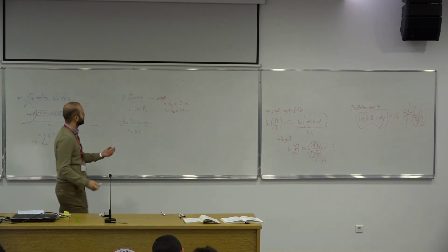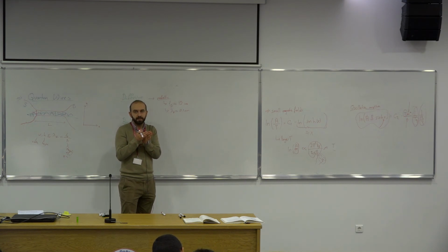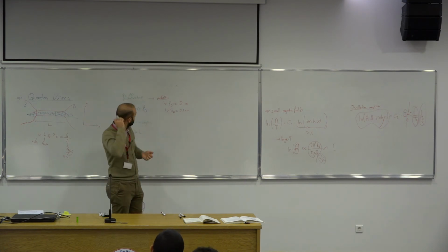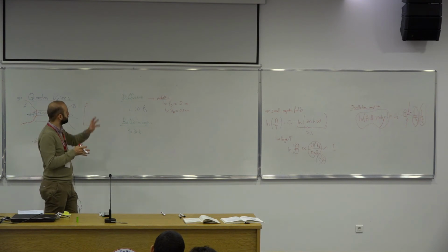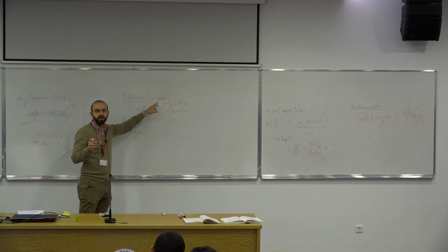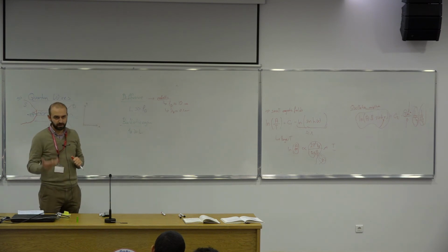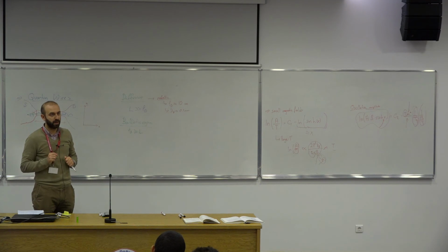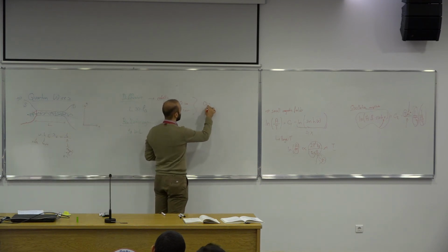So making such a short nanowire is practically impossible, because once you start confining your nanowire to such dimensions, then, as we'll see in a moment, there are other considerations that we have to take into account. So you go to a regime where you start forming quantum point contacts.